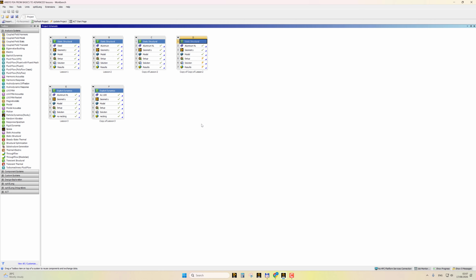Firstly, I would like to remind you that in static structure and transient structure, being implicit finite element analysis, breakage or erosion does not happen or occur. Instead, we need to appeal to what we know as being explicit dynamics, and let me tell you why.